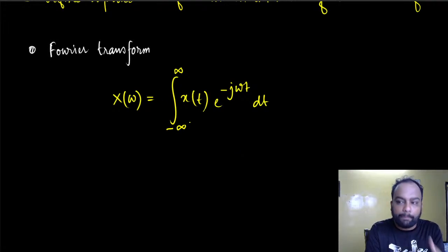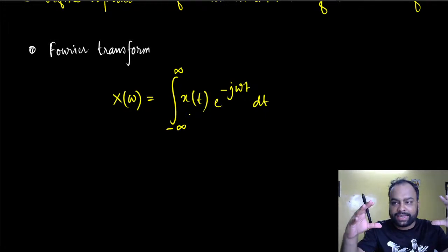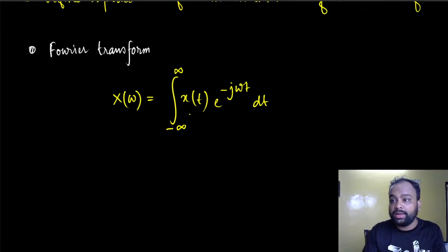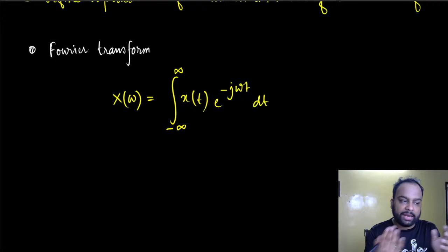If x(t) is a periodic signal that can be expressed as a sum of sinusoids, then we get a Fourier series, which gives you the constituent discrete sinusoids. If the signal is aperiodic, then we have a continuous spectrum of sinusoids, represented by the Fourier transform. For periodic signals as well, you can calculate the Fourier transform. We discussed all these things.